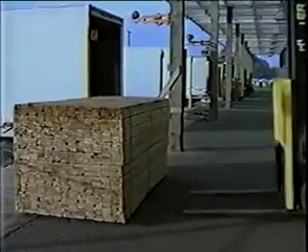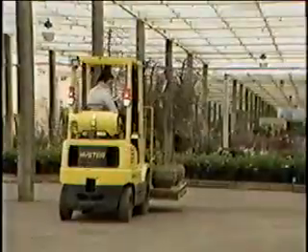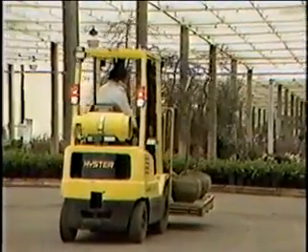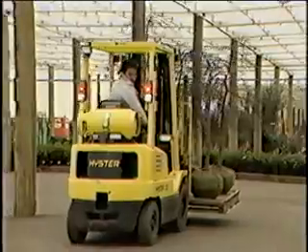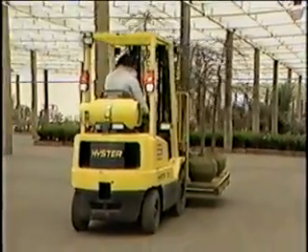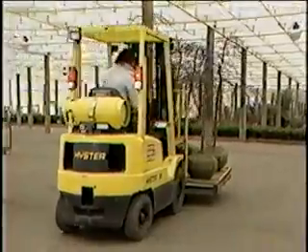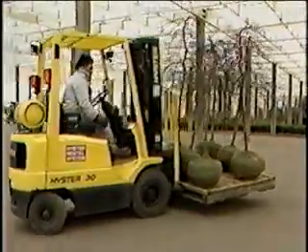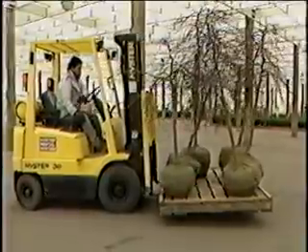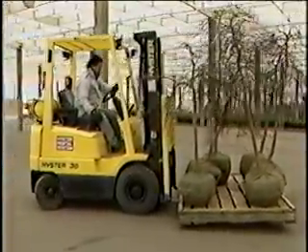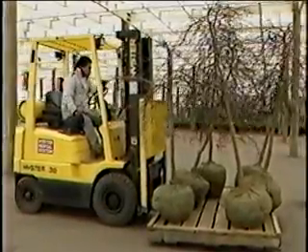The scientific principle involved here is center of gravity. The center of gravity of an object is the single point about which the object is balanced in all directions. It is very important to understand how the center of gravity of a load and forklift combined affects the stability of your forklift while on the job.